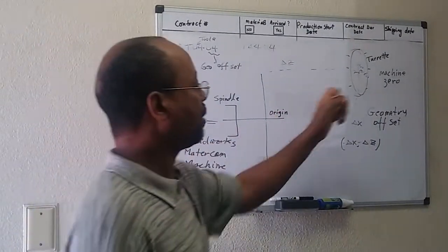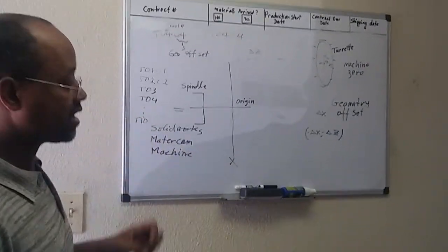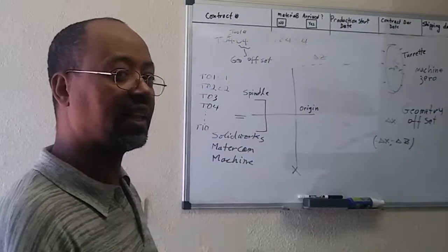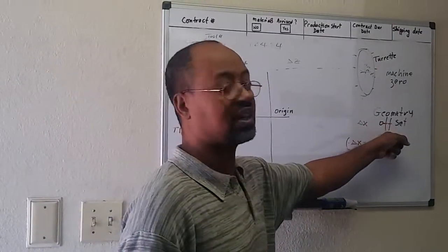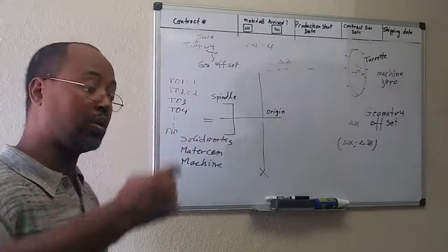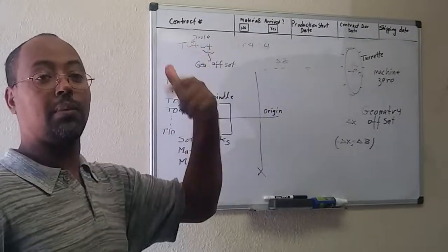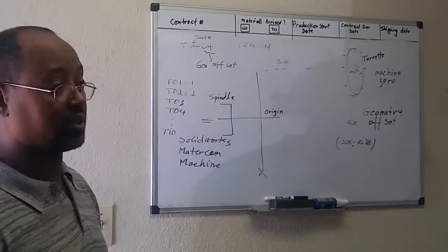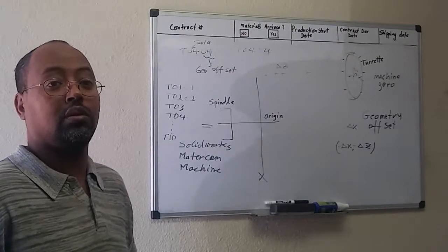Now, in order for the machine to communicate with SolidWorks and Mastercam, I have to use something called offset geometry. Those values would bring the tip location of every tool to the 0 with its respective offset geometry. That's why every tool in your program, when you use Mastercam and try to call them, has the tool number and the offset geometry, as well as the tool location or station, which matches the tool number.